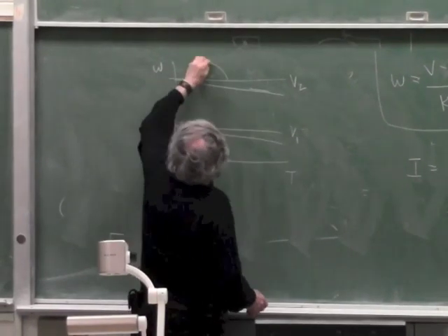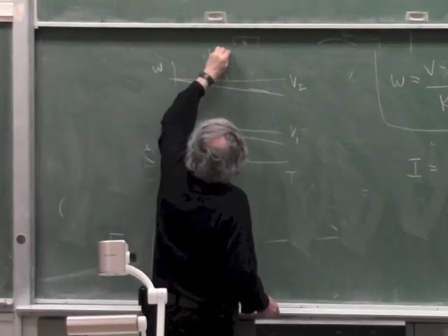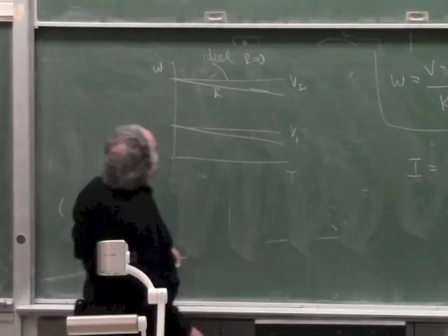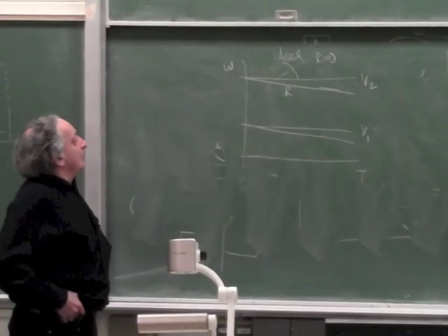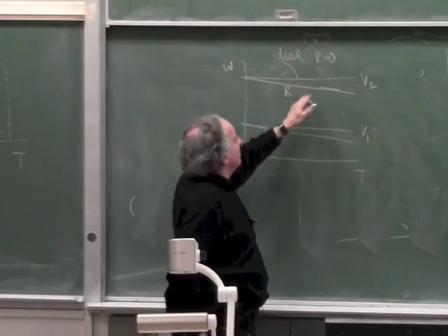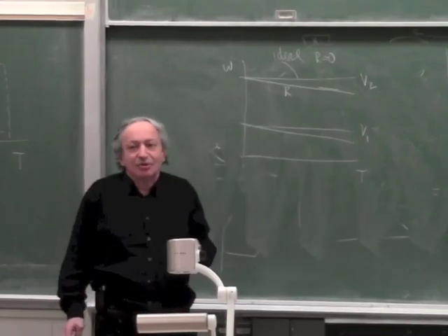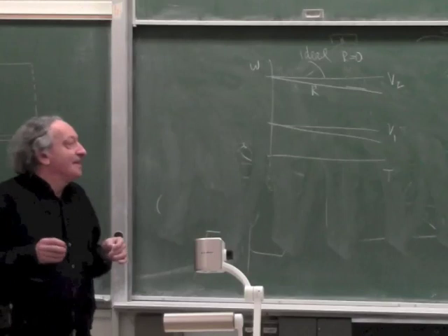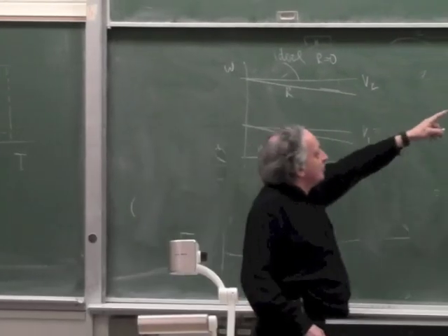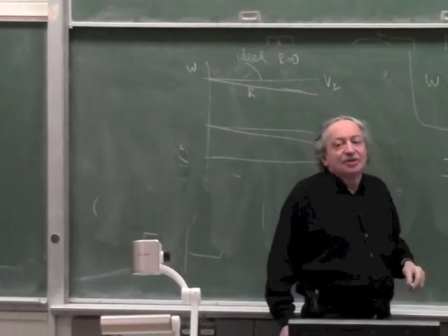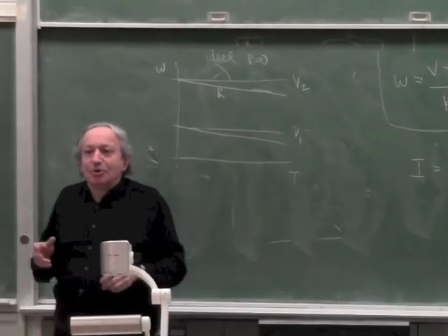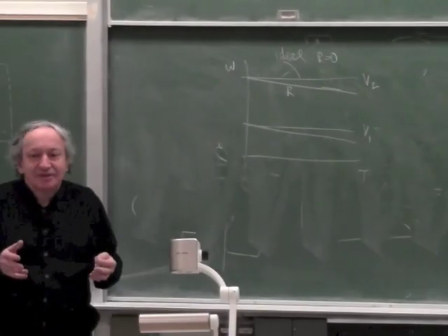Okay, so this is ideal. R equals 0, and this is with a real R. Okay, but you can make this R very small, and matter of fact it is very small, because if you look at DC motors, that R is actually a very, very small portion, and the reason I know that, because I know that motors are highly efficient.